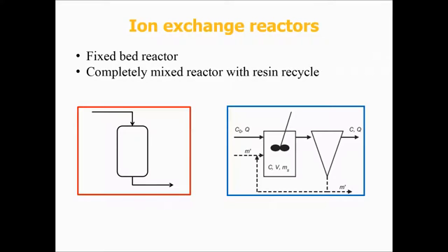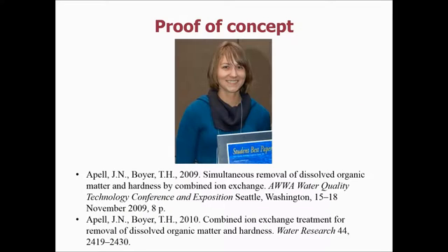One other piece of background information is the reactor configuration. On the left we have the fixed bed reactor that most are probably familiar with for ion exchange or other filtration or adsorption processes, and then a completely mixed reactor with resin recycle, as shown here, where the advantage of this completely mixed process is that the ion exchange process can happen earlier in the treatment train because turbidity and head loss isn't an issue. And so we study both of these processes for ion exchange, and I'll be going back and forth between fixed bed and completely mixed in terms of where our results apply.